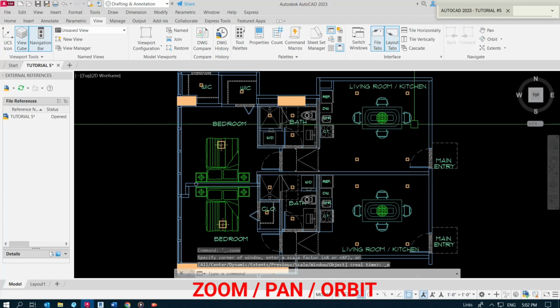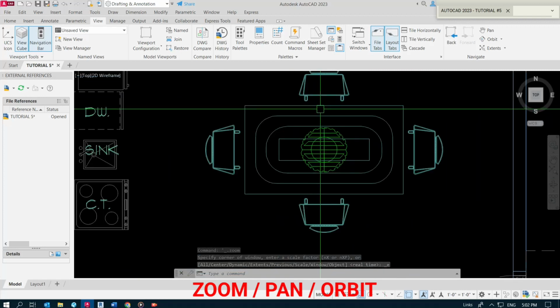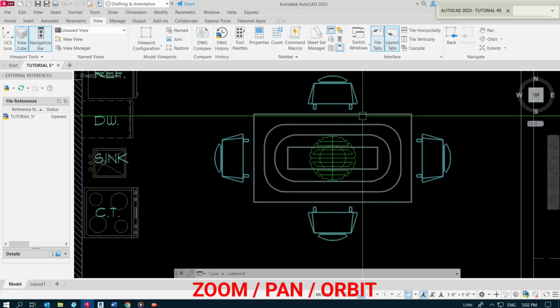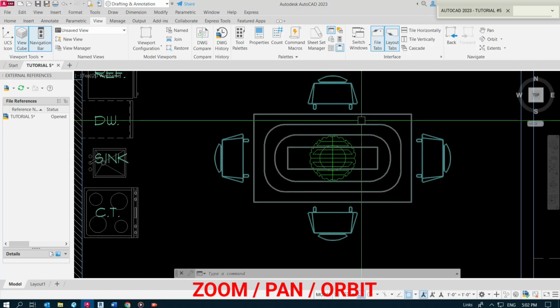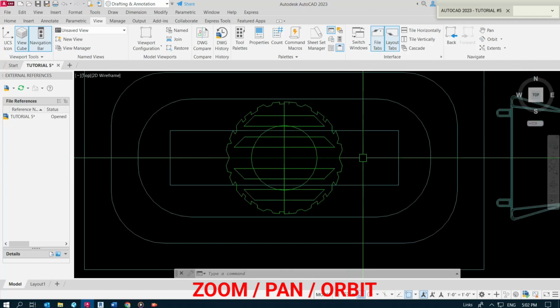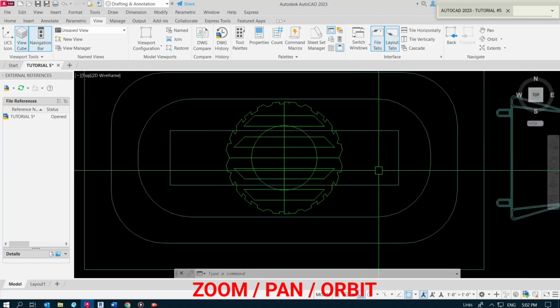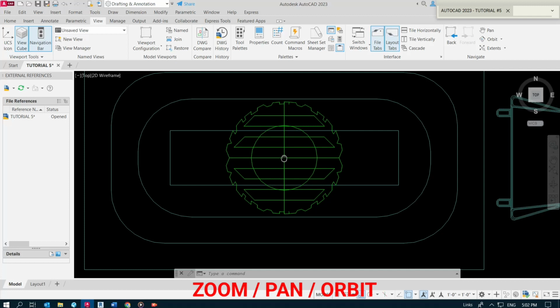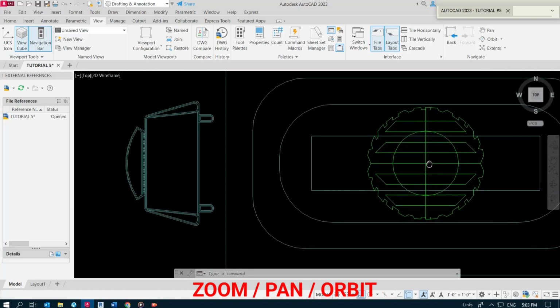Since I am satisfied with the zoom level and the chair is next to the plant, I will just shift the view without changing the viewing direction or magnification. I will hold down the wheel button and drag the mouse to the right until the chair is almost in the middle of the screen.